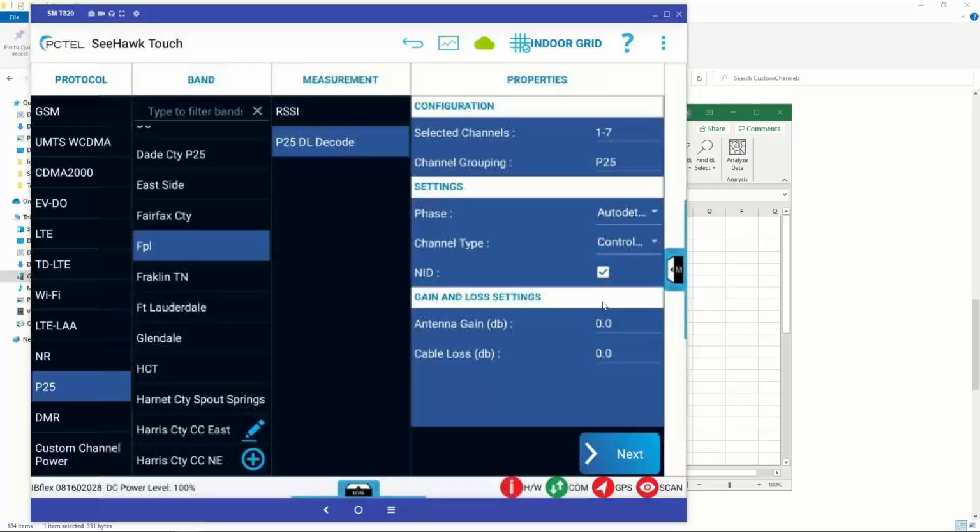You noticed that, eh? Well, it puts us in a high-level theoretical theater, but then, as you mentioned, we've got all the variables. And this is great to see if we wanted to hook onto our donor antenna for a BDA. If they're reporting something, we can look backwards, adding the right gain, and say what's coming into our BDA from our donor? What are we seeing from the towers around us?